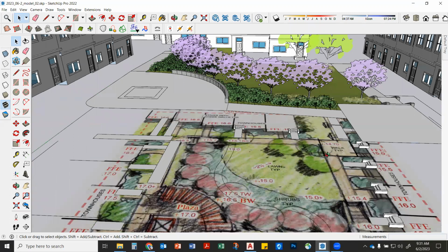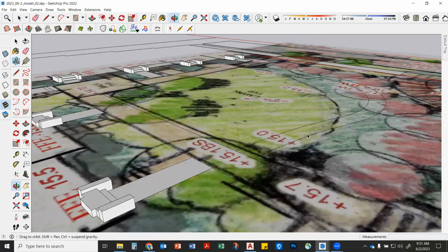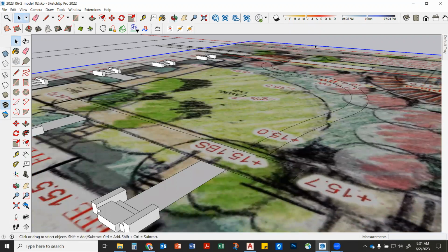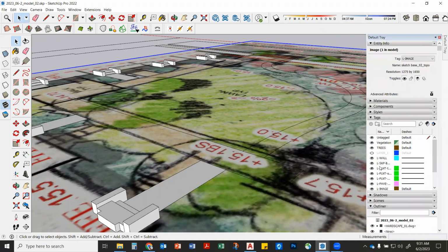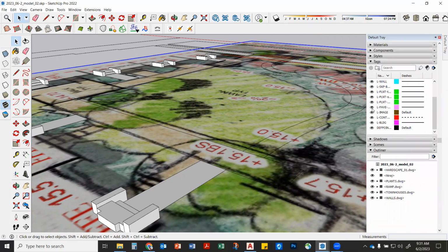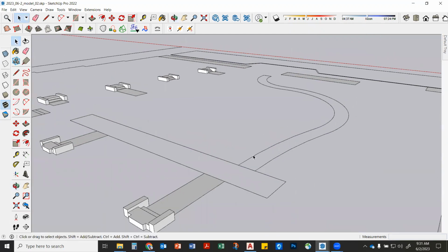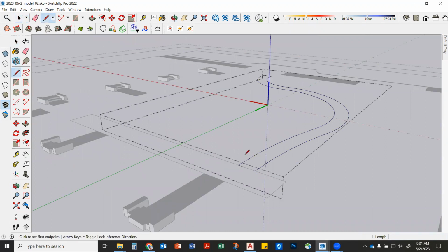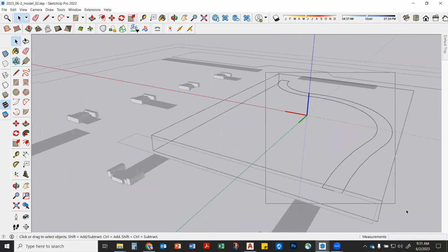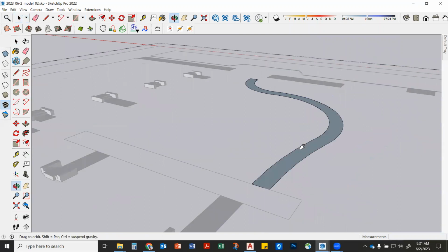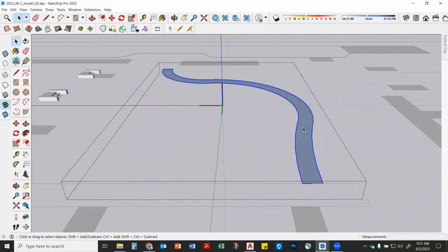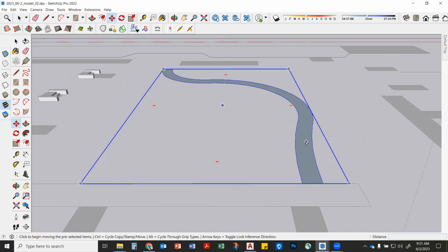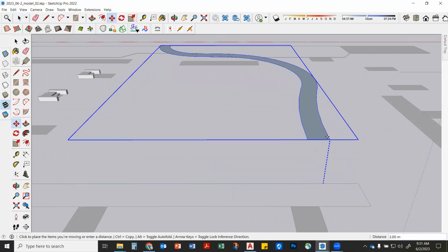Now look, this thing, the ramp, if you guys can see it, I'm going to go ahead and make it a face. My image keeps getting in the way. There it is, right? Now, one of the things that's a little bit tricky, this is a closed polyline, so I could just grab it, and hopefully if I click tools, make faces, it would make a face. Now, there's a couple ways to do this, but I'm going to do it this way first. I'm going to move this up. This is not how I would do it, but it is an option.